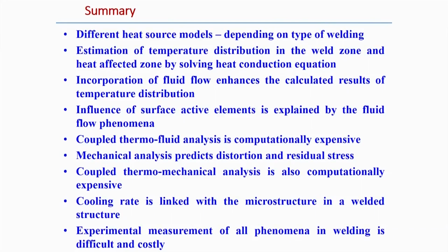And the effect of surface active elements is better explained by incorporating the fluid flow phenomena in the weld pool simulation. But the point is that coupled thermofluid analysis is definitely computationally very expensive. So, in most cases we neglect the fluid flow analysis and do only the heat conduction analysis.